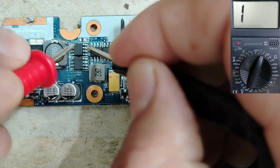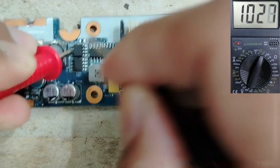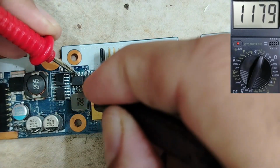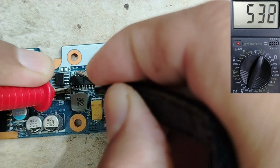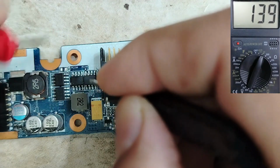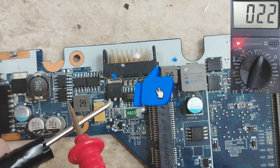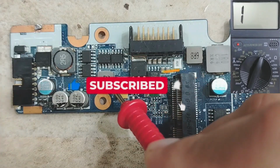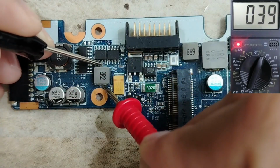For this one also, we can check between drain and source. We get a reading, this is good. Those also the same, we get a reading. If we swap the probes, we get a reading here. Also here, we get a reading, means these 4 MOSFETs are good. If you hear any buzzer like this, it means the MOSFET is shorted. For the inductor, the same as this one, we should get a continuity.